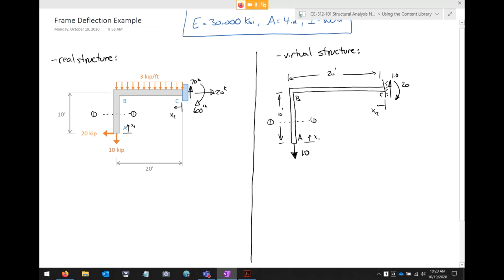All right. Now, what about the horizontal member, the BC, the beam, if you will? If I use the term column and beam, the beam is the horizontal and the column's the vertical. How many sections am I going to have to cut through the horizontal member to fully define that response? One, exactly right. So we'll cut something like this and like this.